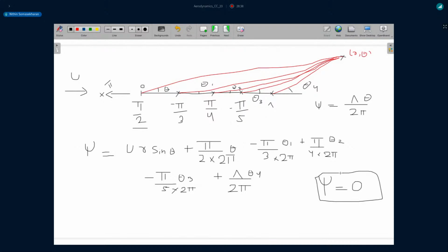And this is basically the parallel that we are drawing from the Rankine half body, because they are very, very similar scenarios, right? In the Rankine full body, you have a source and sink of equal strength, making a closed streamline. Here, the idea is to create a similar scenario. That is, you want the resultant of all these, plus some additional source that we're keeping here, to create a closed body. So we're just trying to draw this parallel.